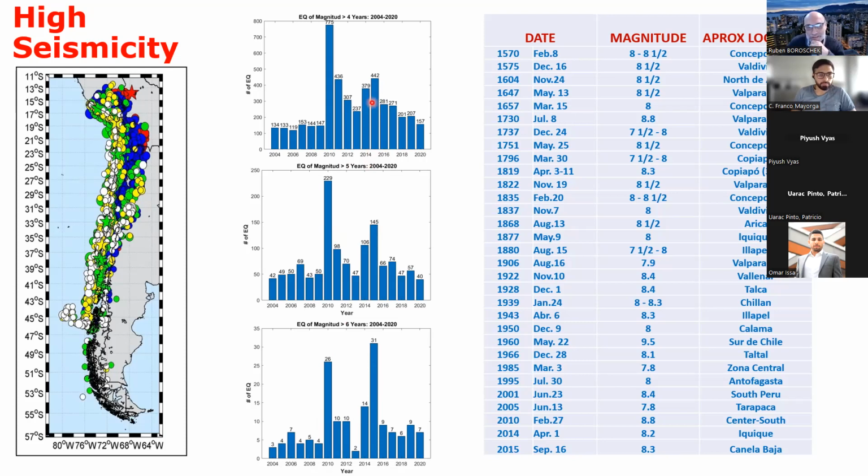But we don't design for this, except that we design for no damage on those low level earthquakes. Actually we design for our extreme earthquakes, that we have plenty of. If you only count the magnitude 8 that produce accelerations between 0.3 to 1.2 G recorded already, we have one every 15 years. We have a magnitude 8 with accelerations close to 0.4 G every 10 years. And of course, we have the magnitude 9s that occur in Chile around a 300 year return period. And we already have like 10 or 11 of those in the last 4,000 years.